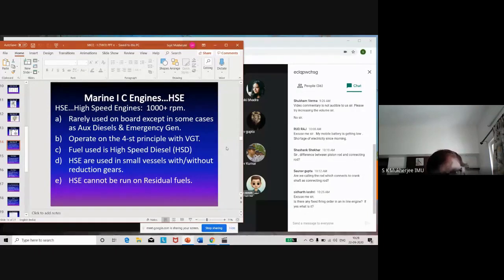Turbocharging is a means of supercharging, and it has been found to be the best because it does not draw any energy from the engine. The other modes of supercharging extract energy to work to deliver air to the engine. So ultimately, overall efficiency is going to drop. Turbocharging is purely waste energy from the engine being utilized. Other forms use the engine energy to allow more air into the engine. There lies the difference. Is it clear?